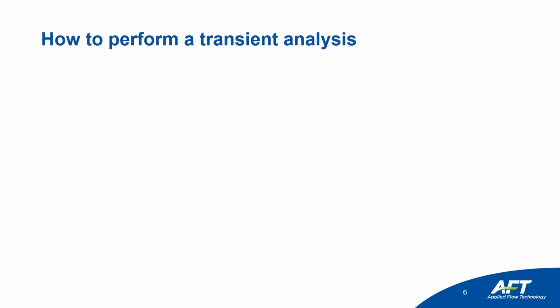So how do we perform a transient analysis? This is something you can take not only for Arrow XTS, but for Fathom XTS and Pulse xStream. Again, creating kind of a framework across all of these different applications. First, I would calibrate or confirm your system in steady state. So you're applying a lot of changes by creating an analysis in the transient domain or over time. So it's important to make sure that your system's calibrated, that steady state is all figured out. So that way, when you start your transient analysis, you're starting from a good place.